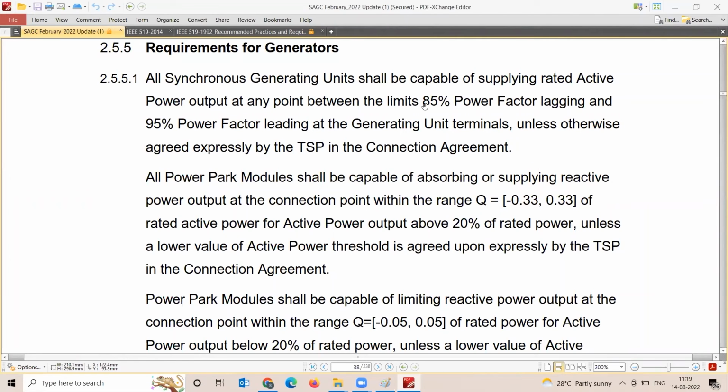You need to optimize the generator transformer OLTC range, and the generator power factor. This limit ensures that, irrespective of the capacity, you need to ask for a generator rating of 0.8 power factor lag. Else, you need separate reactive power compensation. So this decides three aspects. What's the OLTC range of your transformer? What's the impedance of your transformer? That impedance decides the generator circuit breaker rating, and it also dictates the reactive power capability of the generator, the power factor of the generator on the lagging side.